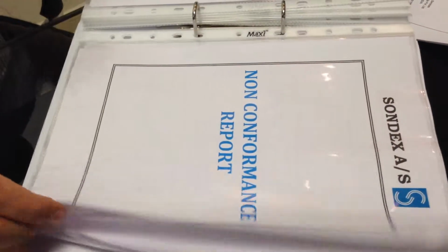And then we have this, the calibration report of the gauges. So the same gauges we are using for the pressure testing, this one. This is the non-conformance report. We had some issues with gaskets. I have written that the gasket is peeled off during testing or at installation time. After that we have written that the damaged gasket will be replaced with a new gasket before the final testing of the heat exchangers.